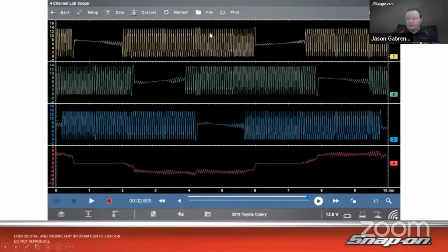I can see whether the polarity is up or down by also adding this other channel over here for my current. I could do one voltage with the current at the same time and see what's going on there. We can see that as well, just to understand how the voltage and current flow through that. But this is a definite multi-channel necessity if you want to test how one of these works, just because it has so many different control signals.